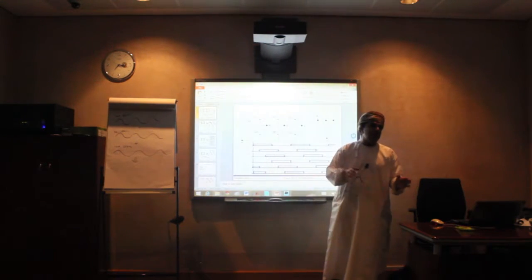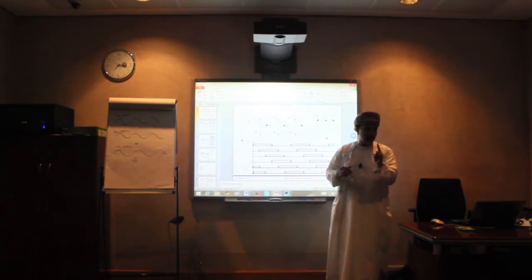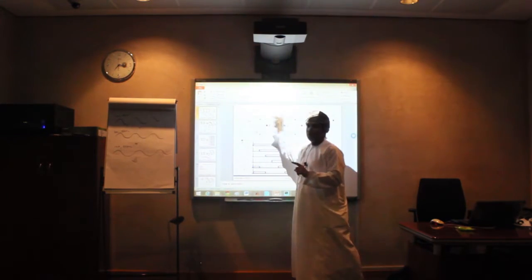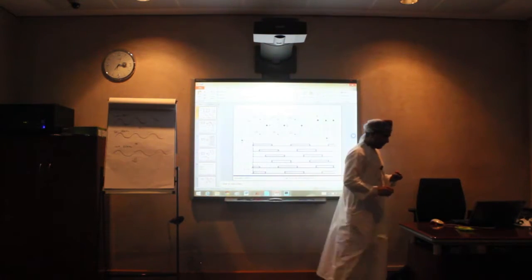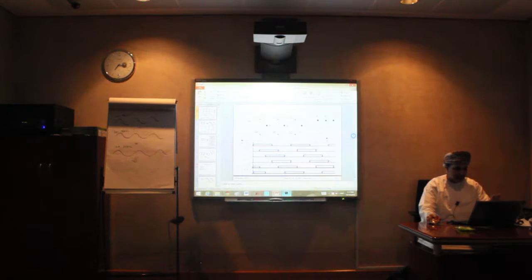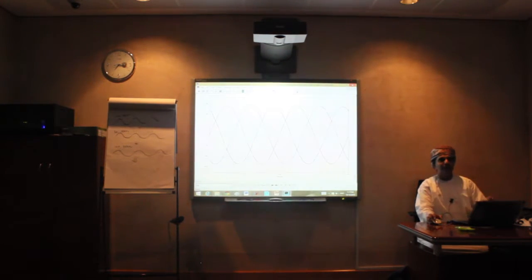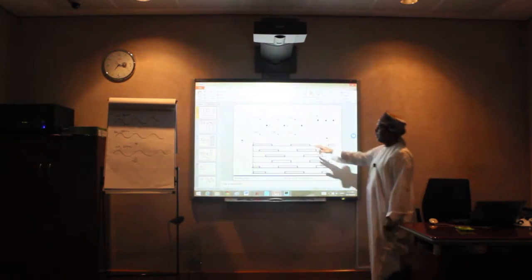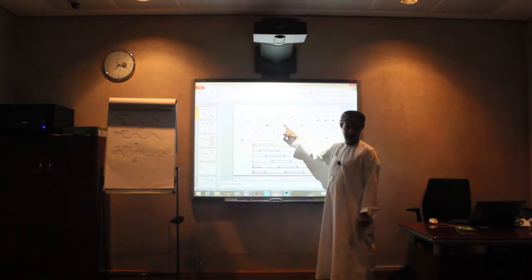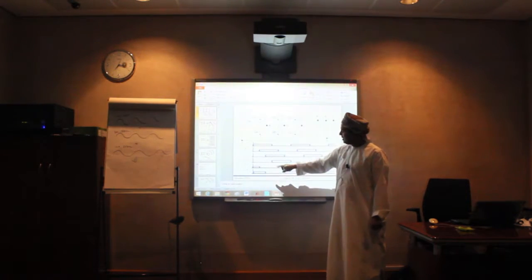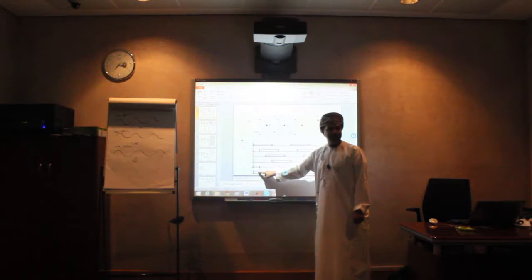And there should be at least one switch on from the bottom side, while there are two from the top, one from the bottom leg in order to make one complete loop, right? So if I look at my target, the blue one, which is B, should be on, right? The blue one from the bottom leg, which switch is that? This is B, the blue phase, right? From the bottom, connected to Q6, right? So therefore I designed my signal here to turn on switch 6.